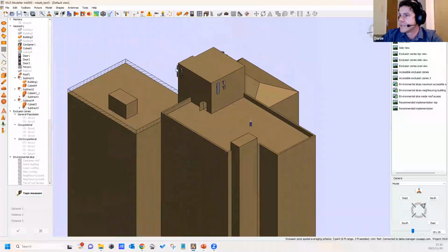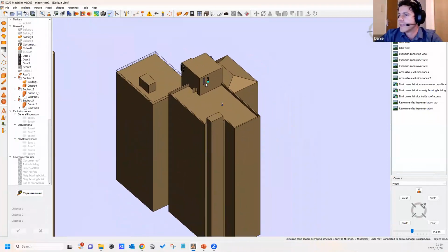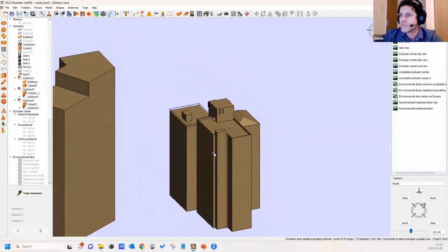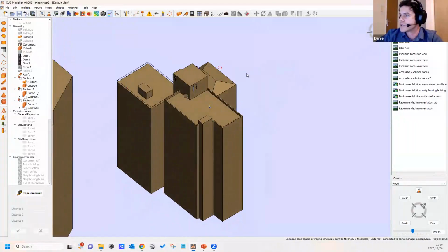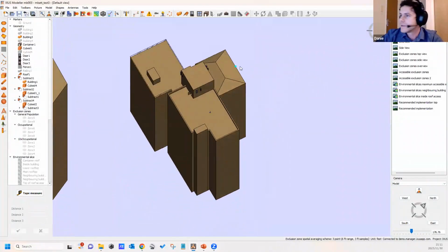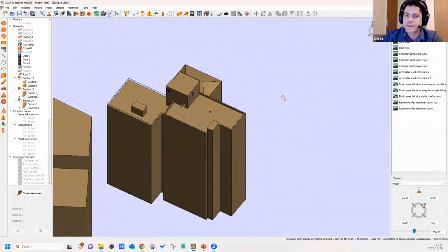However, as you can see, the antennas are located here on this, it's probably an elevator shaft of some sorts. And these antennas would then typically radiate from there. And there would be areas where the exposure to those RF fields would be exceeding the particular guidelines. So the problem now becomes, where do we actually stop assessing? Which surfaces do we need to analyze to determine if that area is going to be overexposed?